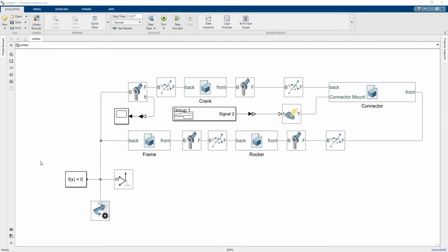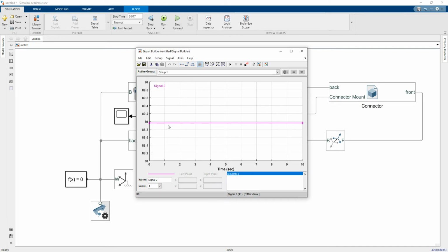There we go. Right, so we've now constructed it, and we've now dropped the linearized load straight onto it. But what's the benefit of using constant value as opposed to signal builder? Signal builder in this case is great. We can have multiple choice between each offset.